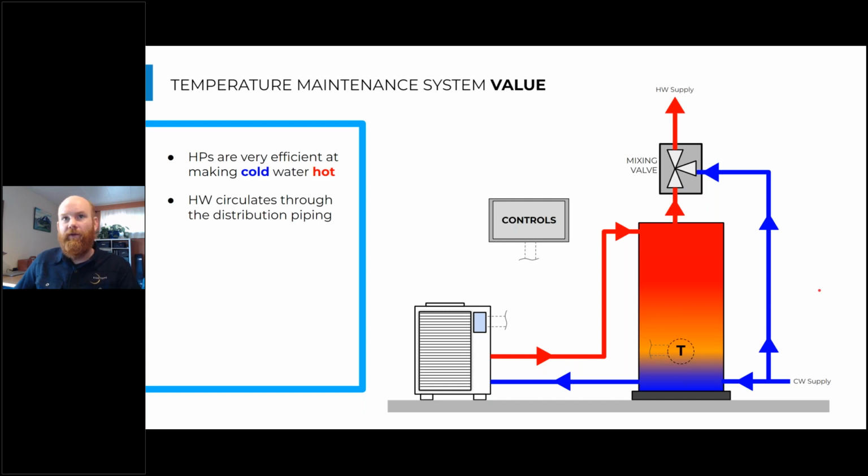In our commercial buildings, we will often have a mixing valve. The hot water, because we might be storing it at 140 degrees, is often a reason to have a mixing valve. There are other reasons as well. That 140 degree water feeds into the hot side of the mixing valve. On the other side, we have cool water coming in from the city, typically around 70 degrees Fahrenheit. That water then mixes out and is delivered to the building fixtures closer to 120 degrees Fahrenheit.